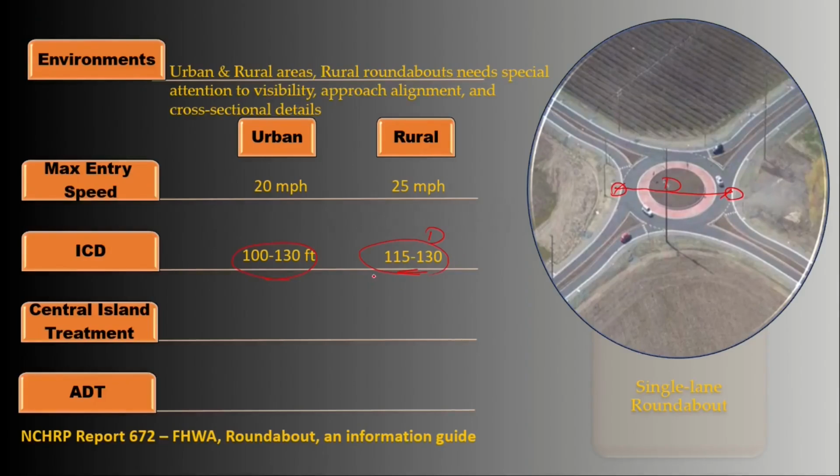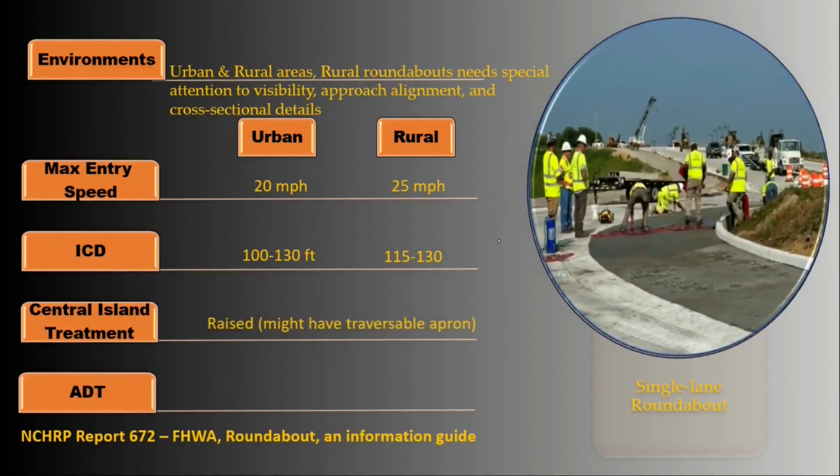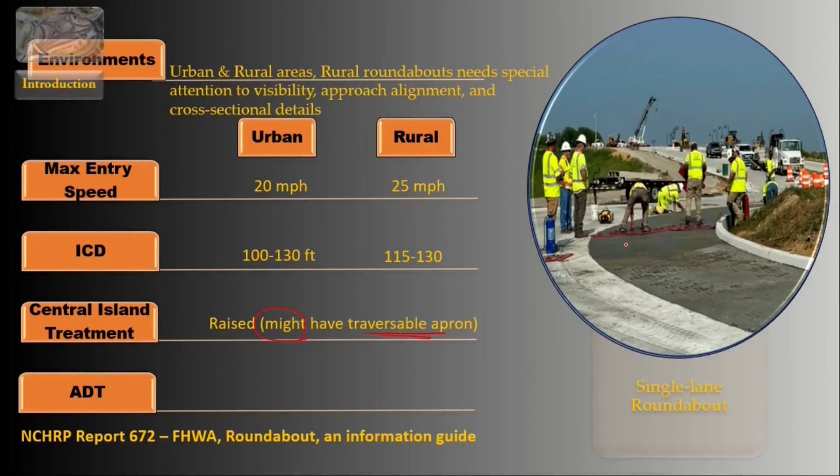As we just discussed, single lane roundabouts normally have a transversable apron to accommodate the width of turning large vehicles. This slope is normally 3 to 4%. And how wide should the apron be? We'll discuss this in the next section using AutoTURN software.